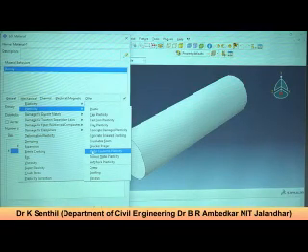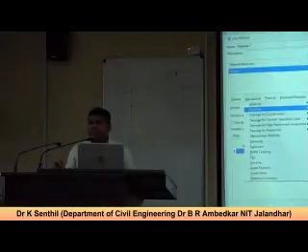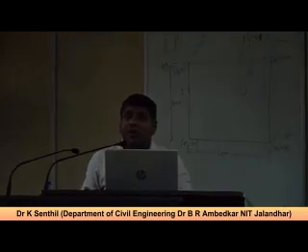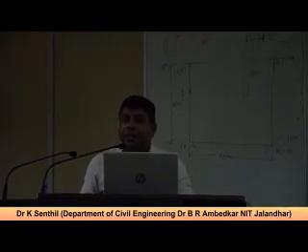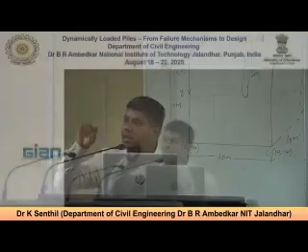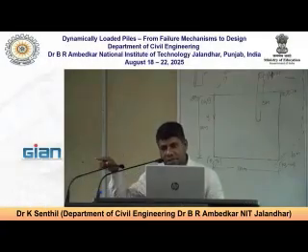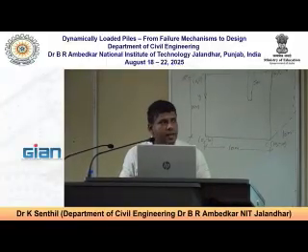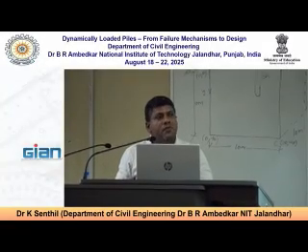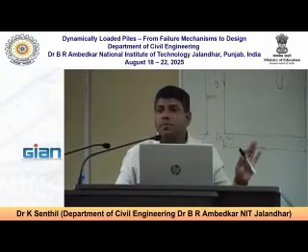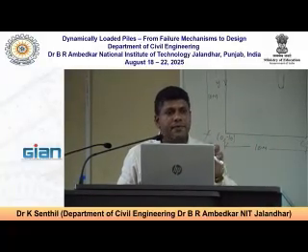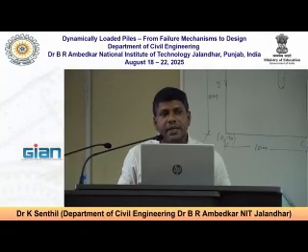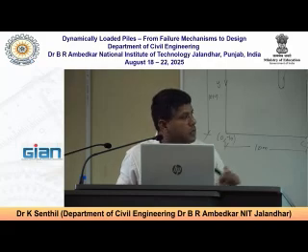Otherwise, for example, I'll tell you, the concrete, we work extensively in India, the concrete damaged plasticity model. In the last 15 years I couldn't find anyone characterizing the concrete. They just put a grade of concrete and get a compressive stress versus strain behavior, and tensile stress versus strain behavior. That's it, and nobody does more. Similarly, for soil also, I couldn't find anyone who actually characterizes even the Mohr-Coulomb model parameters, because they just pick from the literature. See, we need very simple tests, but of course some of the tests need advanced equipment. Okay, so you can select any one.